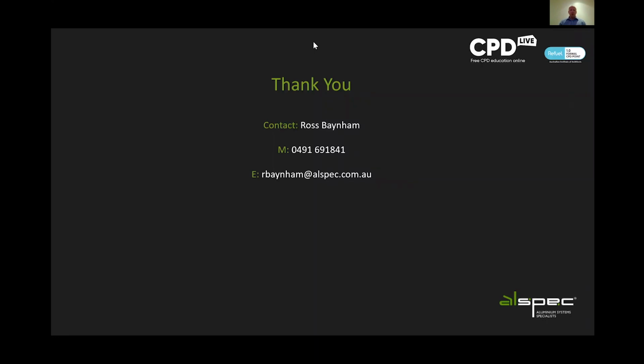Is the thermal break in a window certified as non-combustible? No. There is an exemption within the National Construction Code for thermal breaks for non-combustibility. Essentially, you can't get a non-combustible thermal break. All of our systems are aluminium, but the thermal break part has been exempt from the National Construction Code, AS 1530 Part 1.